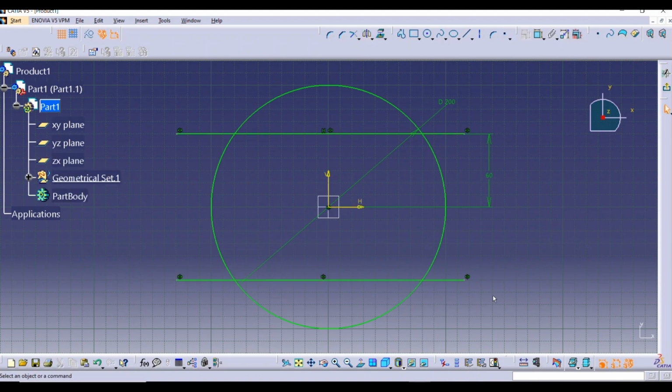Here you can see that the line is completely mirrored, and we get this from here. So I just need to remove this extra stuff. For that purpose just go here, select the quick trim command, double tap on it, click on that, double tap, so that you get it activated. Okay, and I have to remove this thing also at the same time, as well as this. So this is the sketch which I require.